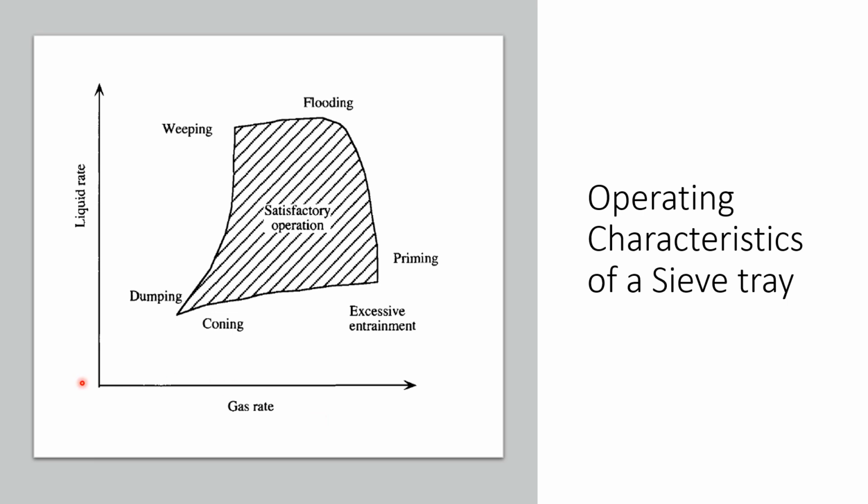However, as a design constraint, if we keep increasing the liquid flow rate, it's true that the column will be smaller and shorter, but we might reach the flooding point or the weeping point. So the design constraints for increasing liquid flow rate are the flooding point, the weeping point, and obviously on top of that the pressure drop.